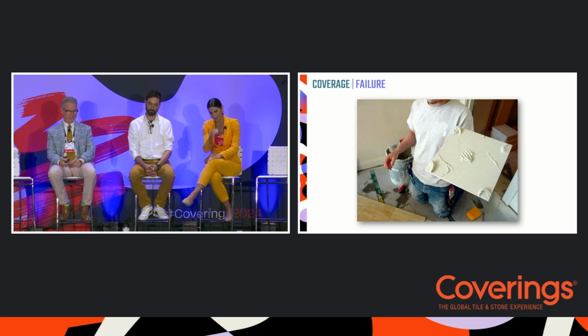And this is what we mean by spot bonding, and sometimes this is done by installers who don't want to struggle with having to maneuver the tile in place. They want it to be very easy to lay the tile in place. So, and this is wrong. Under no circumstances should this ever be done. Unfortunately, we do see it done by installers who haven't been trained or who maybe don't care, and I hope they haven't. I hope everybody cares, but so let's say they haven't been trained.